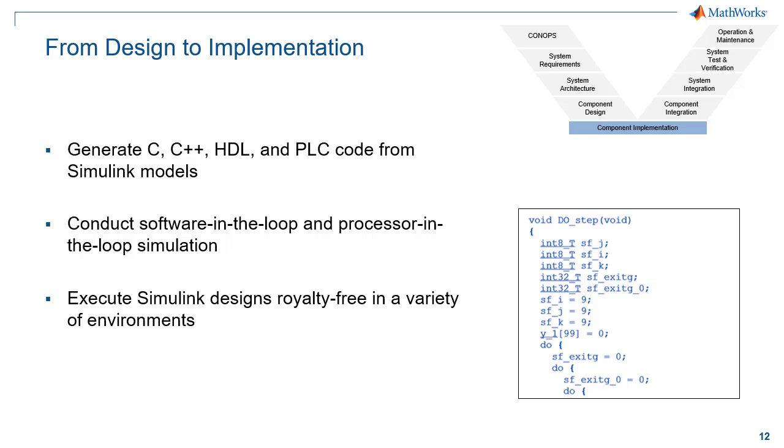So if you want to remain inside the Simulink environment and yet run your model as code, or portions of your model as code, we have a couple of modes available to you. We have a software-in-the-loop mode and a processor-in-the-loop mode, the latter of which runs your code either on an emulator of your board or on some other board connected to your desktop machine. But in all cases, once you're completely divested from Simulink, what you have is a royalty-free instantiation of your design.